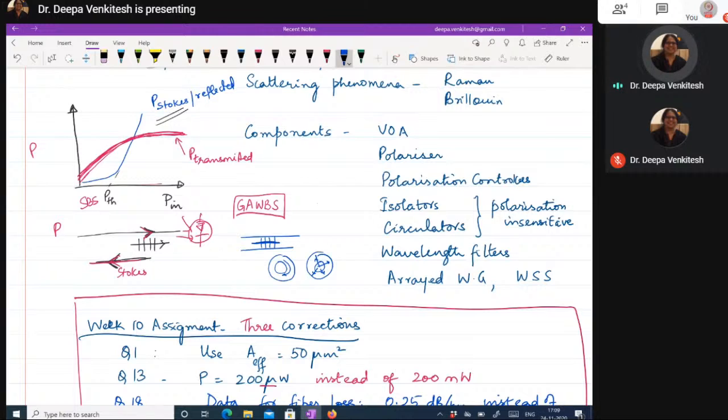It is first of all very, very weak, and the frequency content looks very different, but that could be a source of noise in forward Brillouin scattering, especially phase noise. And in coherent communication, that is considered to be one of the limiting, fundamental sources of noise, right?